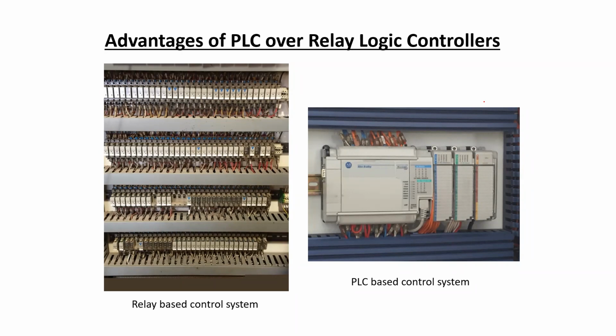Whereas in a PLC based control system, there is only a connection between the input devices and the input ports, and the output devices and the output ports. All the other logic operations, delay operations, or any control process is done in terms of the computer program rather than in terms of physical hardware connections.